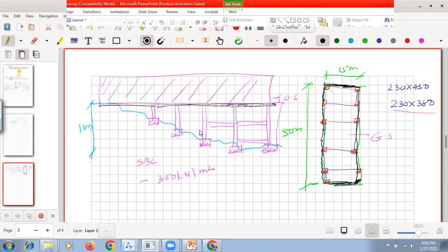So now you come to know what the biggest mistake can be if you are not considering the contours of that particular area. If it is a very small building, say 10 meter by 5 or 6 meter, generally there is not much variation, but you should also see where your project is. In the hilly area, even in a small length, there is a big level difference.